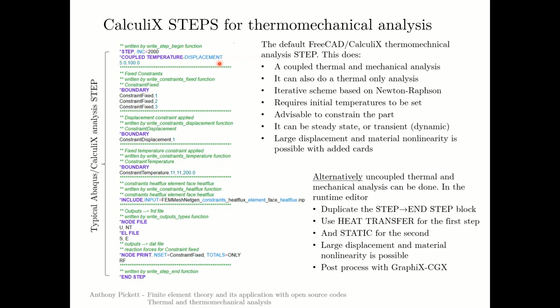And this does one analysis of those previous two I just mentioned, in which a Newton-Raphson iterative technique is used to update displacements and update temperatures so that you have a solution that matches the applied thermal loading and mechanical loading. So it's all done within one step.